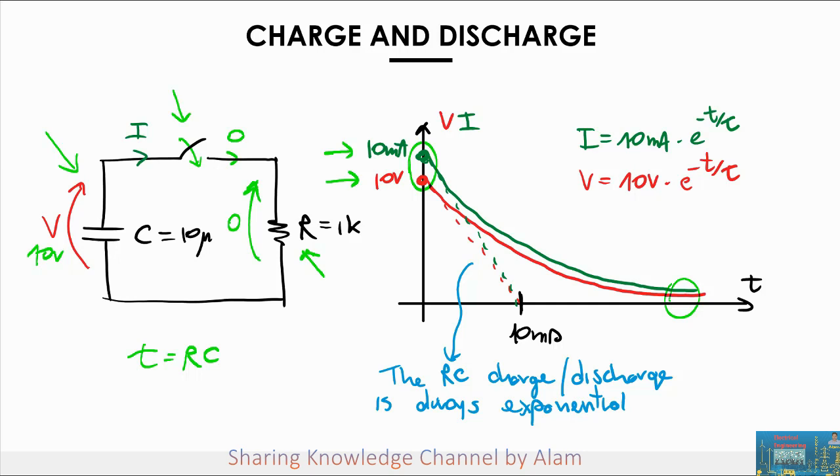That is completely arbitrary. But for both of them, as you can see, I drew the little line connected to the time constant, and then I used that to help me draw the exponential. And up here, I also indicated the formula that gives you the behavior of the voltage and the current. This time, because in both cases we're going from a value to 0, they both look the same. So you don't have the term that is 1 minus the exponential over tau, but you only have the exponential part.